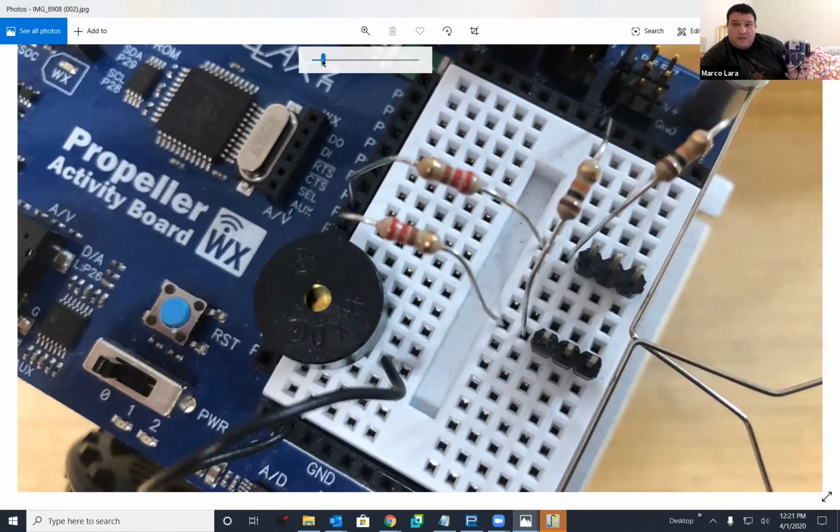Are your I/O pins correct? Starting on the left side, which I/O pins do you have the resistors plugged into? Are they 7 and 8? Yes. And then those are red, red, brown. And when they go over to the breadboard, they are touching each other a little. Are they also connected in the same row as the 3-pin headers on the right side? Yeah. Because in my example here, I have a part in every single hole on the breadboard on the right side, not doing anything.